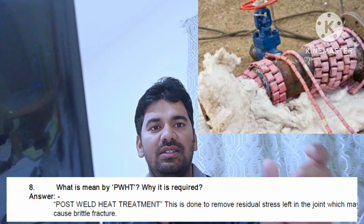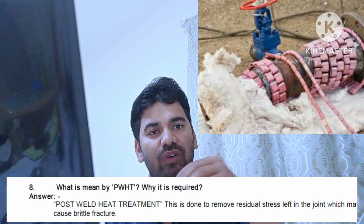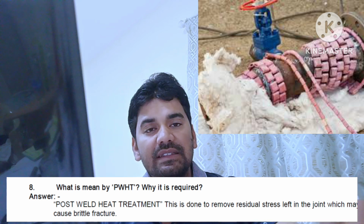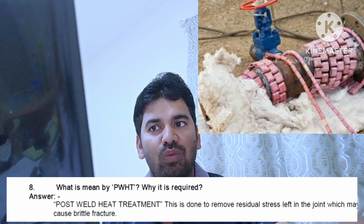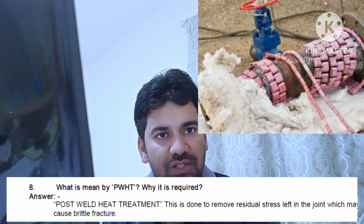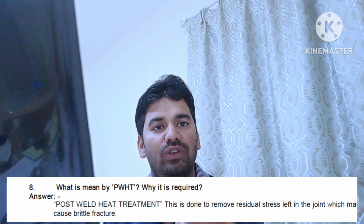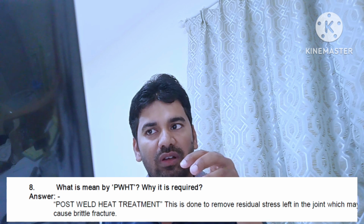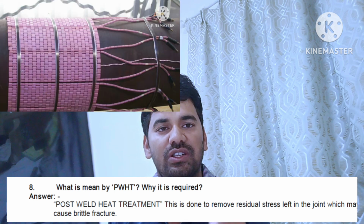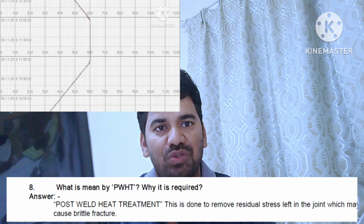The simple answer is PWHT means post weld heat treatment. When the welding is finalized, some treatment needs to be done, and that is post weld heat treatment. This is done to remove the residual stress left in the joint, which may cause brittle fracture. During welding, some residual stress is generated in the joint, so we need to remove the stress because of this stress, brittle fracture may occur. That process of removing the stress is PWHT, post weld heat treatment.